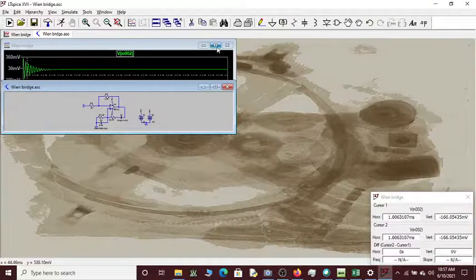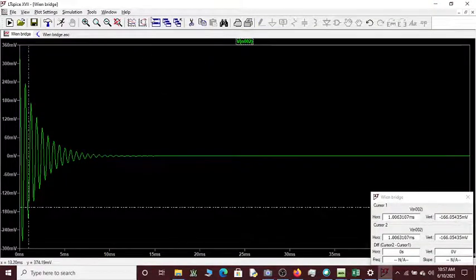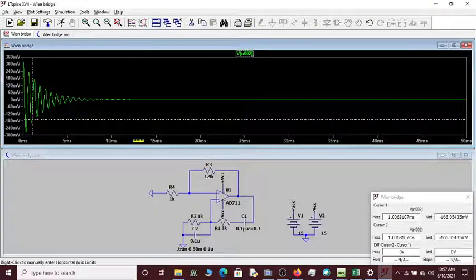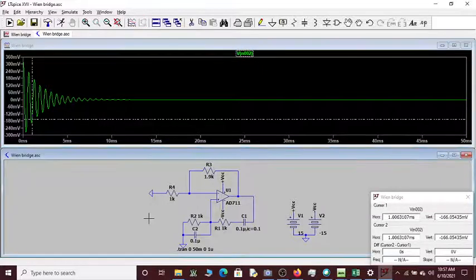So we can do a similar type of analysis by applying some input also here. So what I do is, let me just demonstrate this as a system which is stable, critically stable and unstable. For that, because I know the frequency of oscillation is 1.59 kHz, let me use this as an amplifier now first.